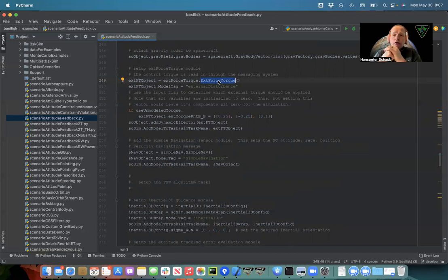But it's also useful if you just want to mimic some disturbance. If you're saying, look, I'm flying in a certain attitude and there'll be some disturbance torques acting on it, and this will generate 10 millinewton meters of torque, you can just specify a disturbance torque instead of having to model all the disturbances in high detail. This is also very useful for robustness checking and control development.